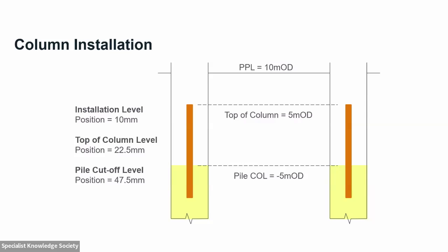This actually shows here that there is a tolerance. As you put your column into the ground, depending on how far below ground you want to cast your floor slab for your initial support, that may well be slightly out of position from where you are at the top, if that makes sense. So your column won't be exactly in the right position, because there will be a certain amount of tolerance.